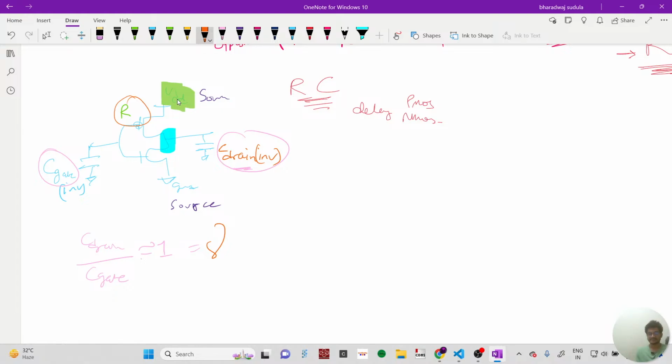Timing analysis tools, let's say PrimeTime from Synopsys, will have some standard cells. Within that there will be some predefined delay values for a standard cell. Those are obtained using these extracted RC values. With these extracted RC values, we find the delays of the standard cells, and those will be used by tools like PrimeTime.